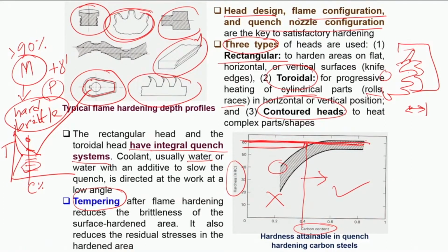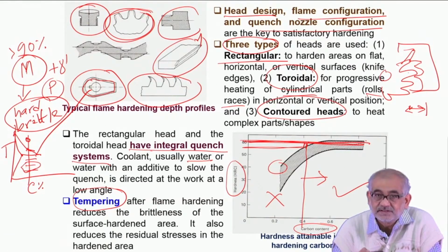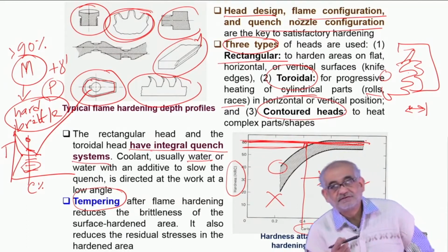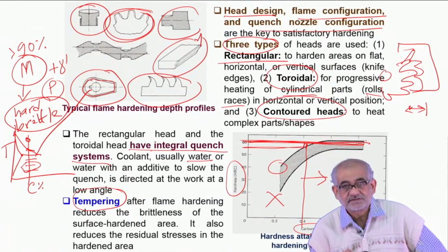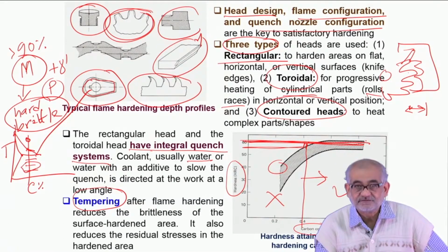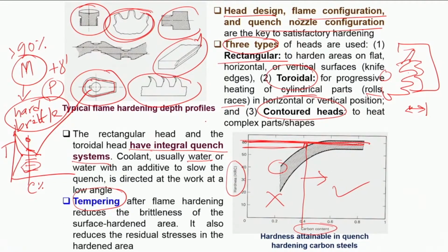If you recall, during the discourse on martensitic transformation, I did mention that one of the biggest reasons for seeing martensite as the hardest solid solution phase is that martensite derives its strength primarily from supersaturation.